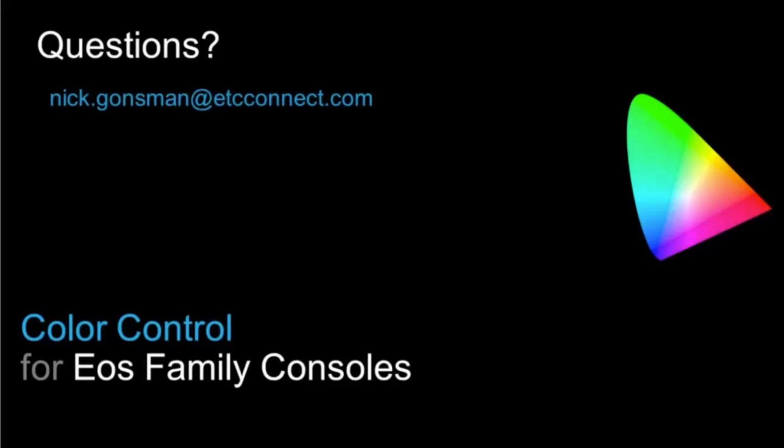So Lustr fixtures, Desire fixtures, those fixture lines all have two types of modes. One of them is called direct mode, which is where you're just hot wired to the emitters. We don't do any sort of math to try and help you get to a better color or to help your fixture to fixture color matching be better, which lets the math in EOS shine, right? It's just great.